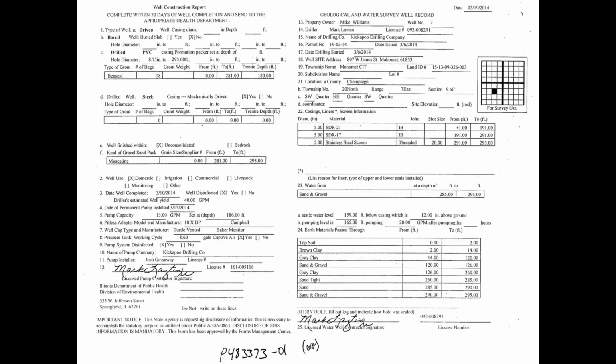And that's usually the best place to put your well screen, because then you can keep all those fines where the tight sand is. That's likely very fine sand, and it'd be really hard to keep it out, no matter how small the slot size was. But here we have sand from 260 to 295 in total, and so they put in a well. And if you go straight up, they're getting the water from the sand from 285 to 295.